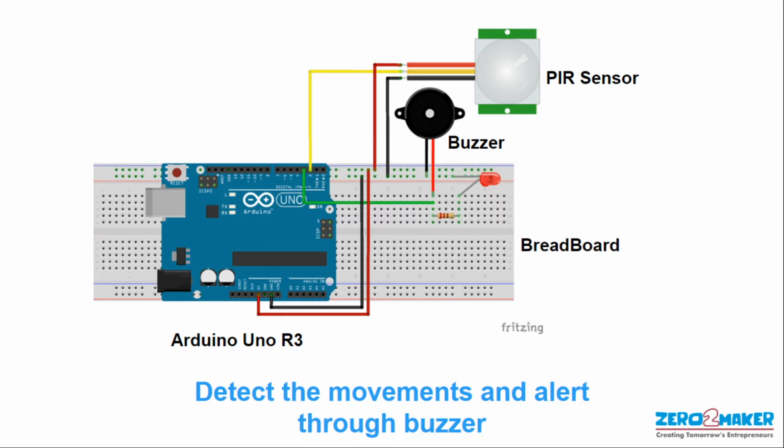The input comes through the PIR sensor, which sends an input to the Arduino on pin number 2. Whenever it detects something, it sends a signal. But to run the PIR, it also requires 5 volts, ground and plus. So we can see from here that we are providing the plus and minus power to the PIR using a breadboard.